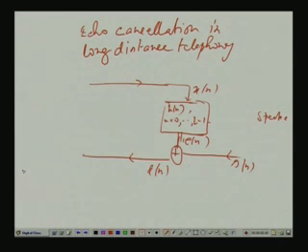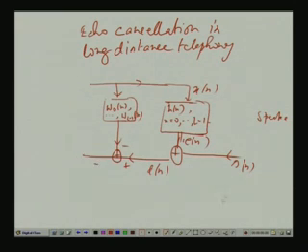To avoid this E n, I put a filter here, an adaptive filter of the same order, say W L minus 1 n, use this signal as its desired response, and take the error. This is the error. So, this is not E n, let me change the symbol E n to something else, let me call it echo n, and this is E n.